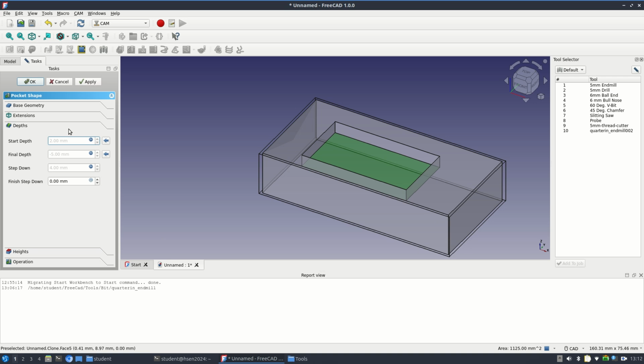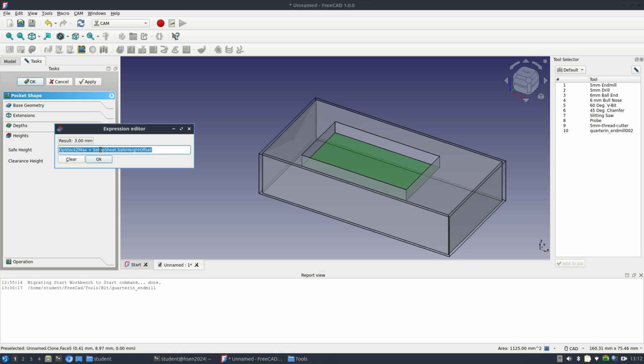Right? So I'm going to do height. Height means, what's the travel height? Like how far the tool is from our surface once it's traveling to get either to the origin or to the tool change position or whatever position there.